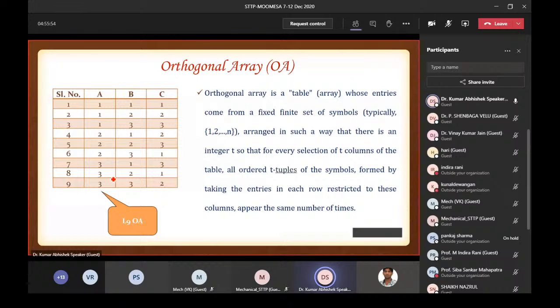So if you see the interaction A cross B cross C, there will be 8. Therefore, whichever orthogonal array I have to choose, it is the one after 8, whichever is the minimum after 8. That is the L9 orthogonal array; after L8 comes L9, so I will select L9. But what is the procedure behind this L9 selection?